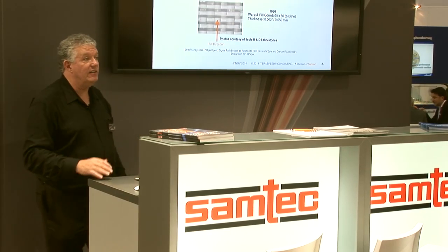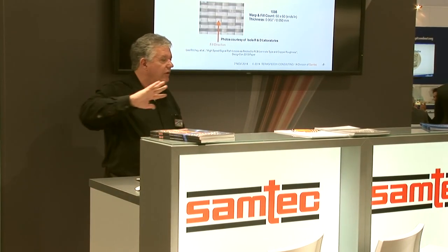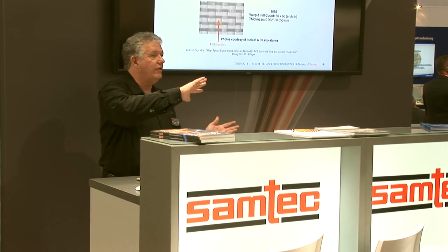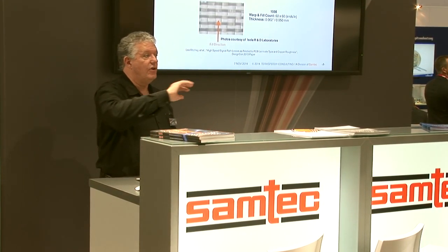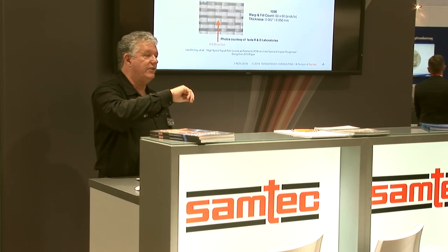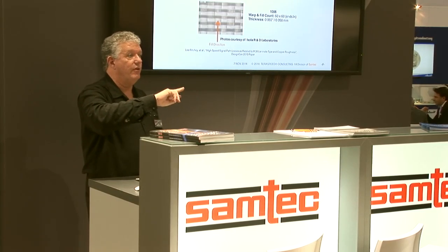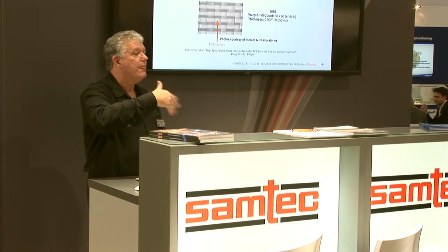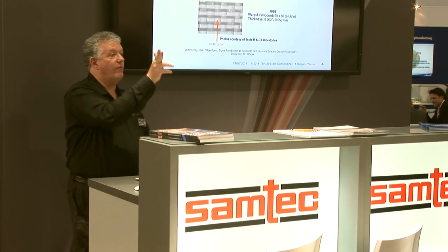So it is possible. And now if you do that and then combine that with some diagonal routing, that does a lot to eliminate as much skew as possible. Because oftentimes when you come out of a device, you have to route parallel. You don't have any choice. So if you can route at the same pitch as the fiber, then you can reduce the amount of skew. And then once you get outside of there, you can route diagonally.